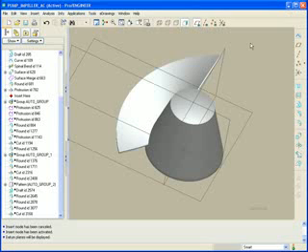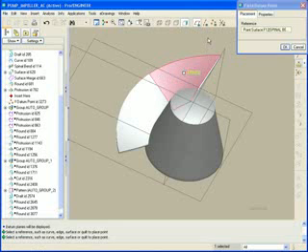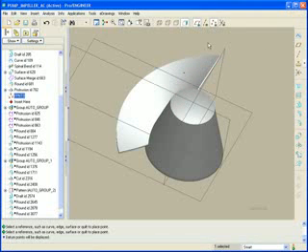So let's build that geometry, doing it just a little different. Instead of just using a regular point, I'm going to use something here called a field point. Now the field datum point provides a point that resides in a domain. So let's just put that point there. You'll notice that it doesn't require offset references. So there's a point on that surface.